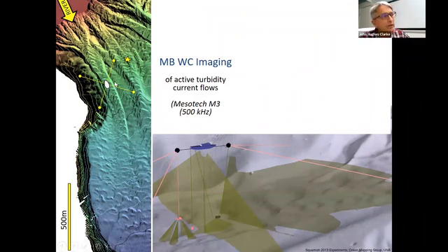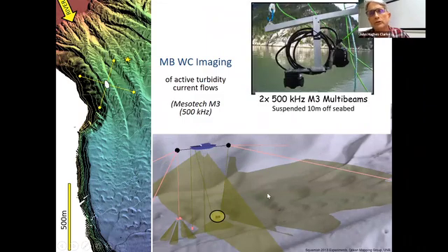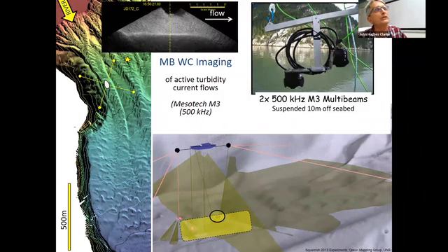So it's really frustrating. So there's another approach, and again, I've been trying active sonars. Very proximally, we'd anchor a vessel, 4-point anchor, and image. And we actually use the LEM3, they're 500 kilohertz multi-beams made by Mesotech, lovely systems. And you can look at the flow as it goes by. You can look straight down, and you can wait for the flow to happen. Hopefully it'll arrive in a moment.